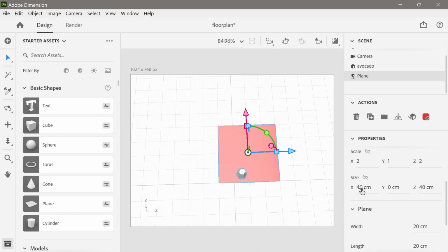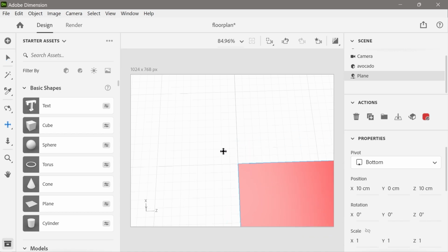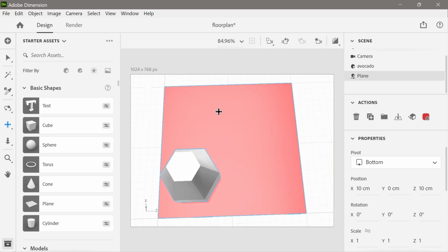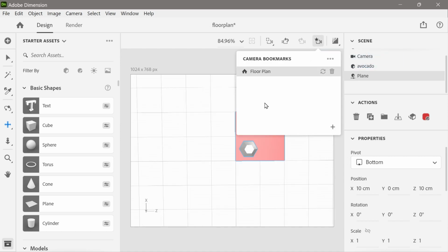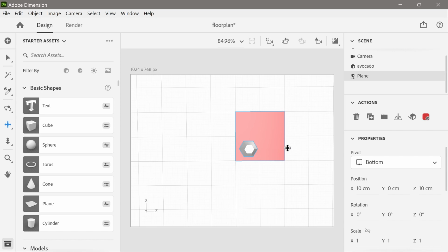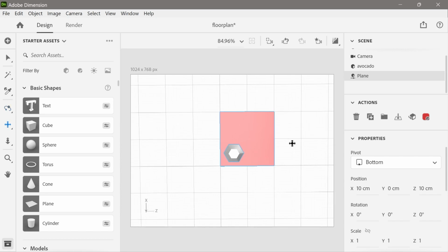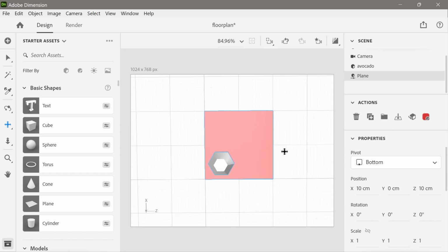All right, let's go back, change that back to where we were, and let's zoom in and see what else we can do here. If we press number 2 here, you can see I'm a bit out of focus. There's different ways to get it in focus. We can press the F key as well, that will get it in focus too. Or we can always go back to, I think it's useful to save different bookmarks for this. That one I found going back to quite a lot. But yeah, 2 is really the pan. If I want to get it more central and then do a zoom, I just use the 2.